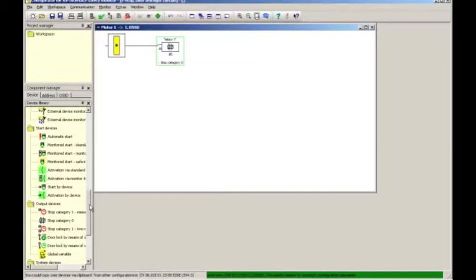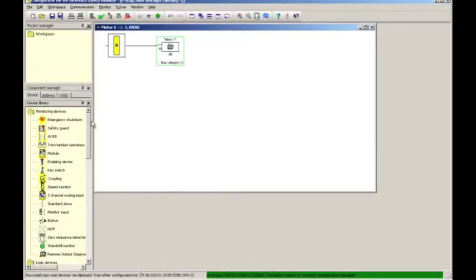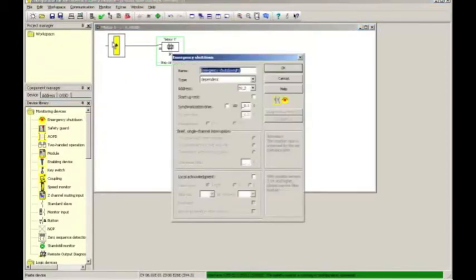Next step is to add the safety devices. We'll start by adding the e-stop, and making that a dependent with filtering type so that we have a little bit of forgiveness in terms of stabilizing the contacts when they close up, and also synchronization. The e-stop is connected to the contact set S1, S2,